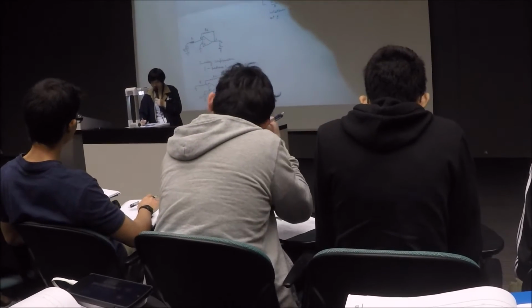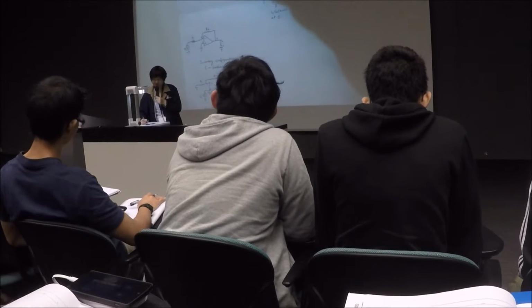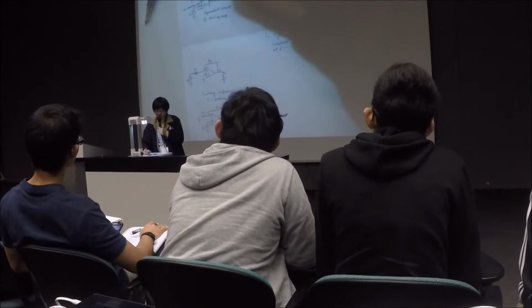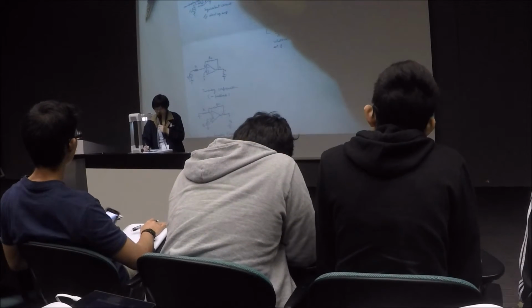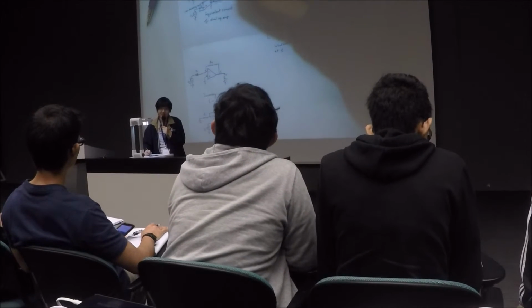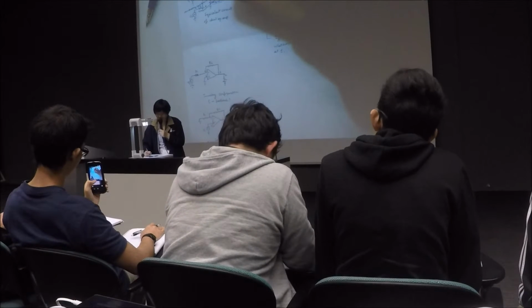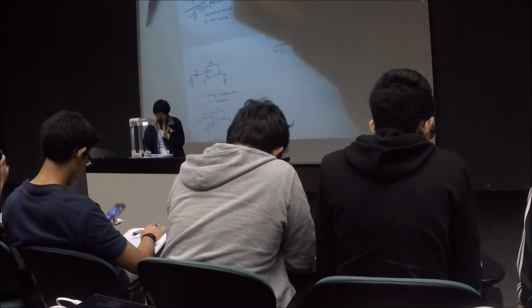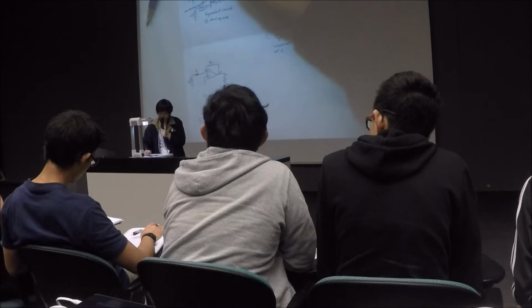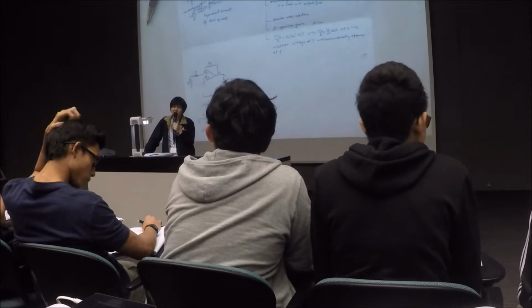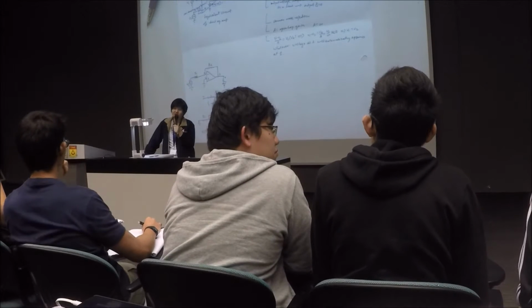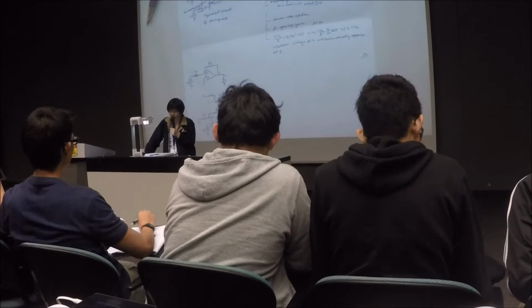Alright, so do remember the grounded point, okay, is at the connection point of two batteries. So it's not at the negative end. So for your op amp, actually no terminal is actually grounded. Alright, so do remember this.